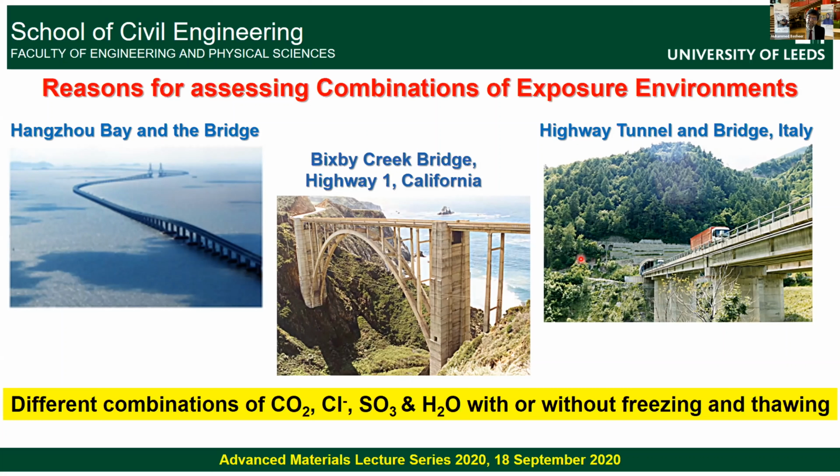So when we deal with the performance of these structures in different exposure conditions, we need to look at the combinations of the exposure environments. So in this particular talk, I'm going to actually use the carbon dioxide and chlorides. That doesn't mean that only those two will have to be applied in all these cases. There will be, for example, sulfate in some cases, and the moisture presence is always there.